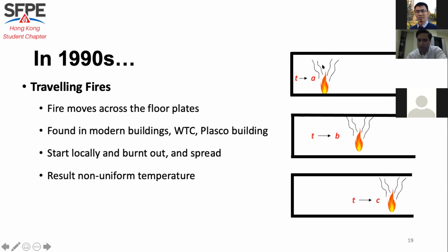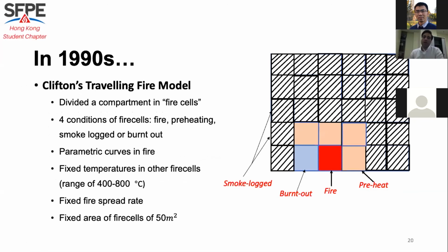Here temperature is burning locally, but what is the temperature far away? And fire is moving here. So you have to take advantage of some models for how far the temperature is moving. None of the previous curves can be applied to this kind of fire behavior, which is basically more realistic than the others. One of the earliest works to understand this traveling fire was suggested by Clifton.